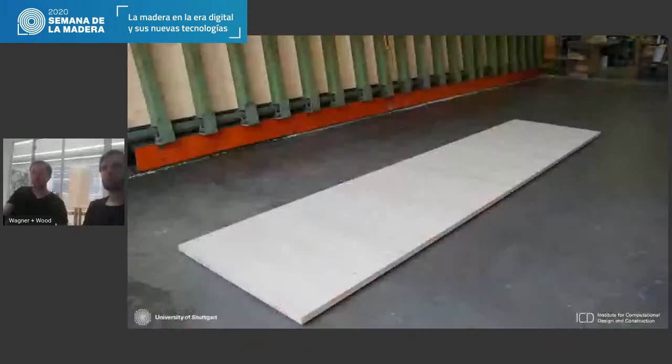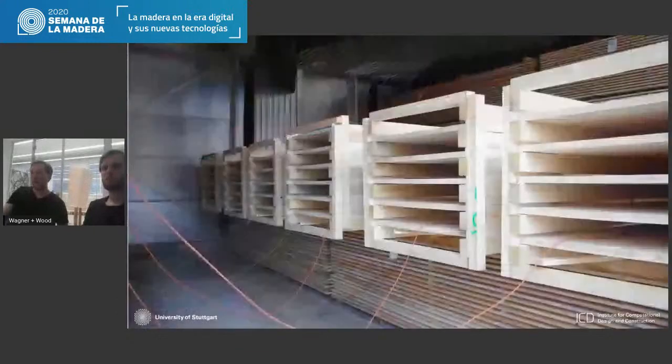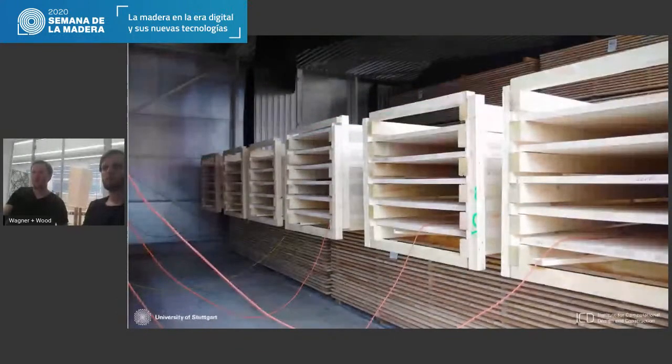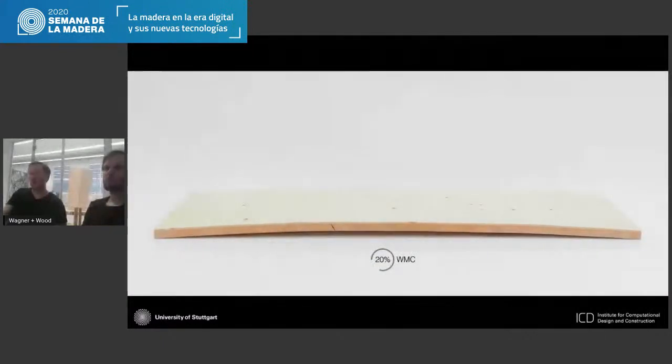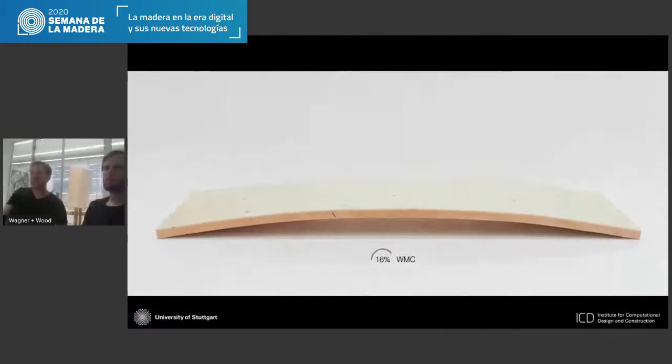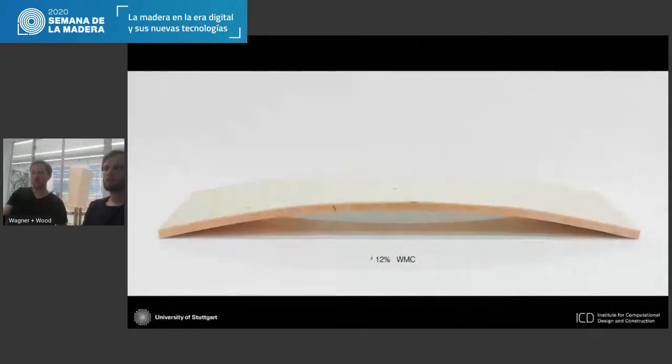After the boards are sorted, we can put them into these large-scale bilayers, as we explained before. And then the bilayers are placed into a standard kiln drying cycle. Inside the kiln, the self-shaping movement is autonomous and smooth, and also clean and coordinated. So this happens almost like magic as the boards are dried out.